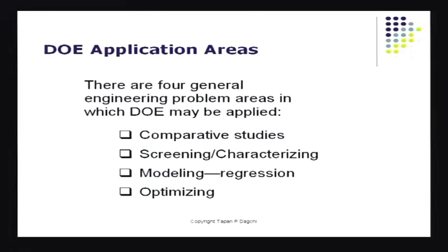Now, what we really would like to be able to do is look at the response, and you'll see in a couple of minutes what we mean by the response of a particular process. The response itself may turn out to be a very crazy function. If you're trying to optimize the process, if you're trying to reach the peak of the response surface, certain special methods have to be utilized there. Certain special design schemes or experimental schemes also have to be utilized. I'm just going to give you a glimpse of it, because later on you can pull up a textbook and study this technique called RSM, response surface method, and that will help you empirically optimize different processes.